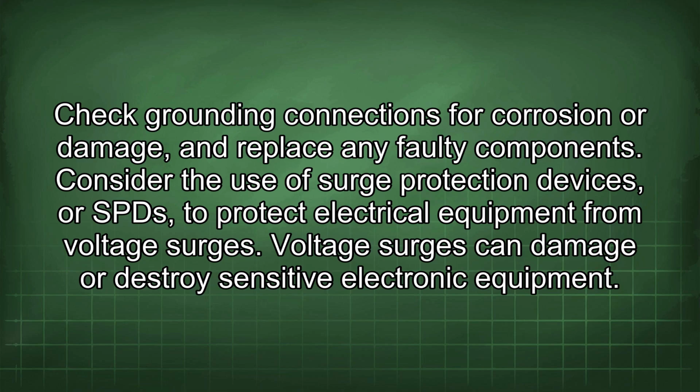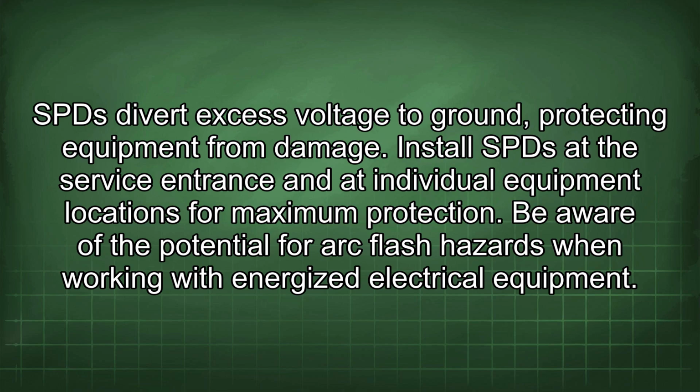Consider the use of surge protection devices, or SPDs, to protect electrical equipment from voltage surges. Voltage surges can damage or destroy sensitive electronic equipment. SPDs divert excess voltage to ground, protecting equipment from damage. Install SPDs at the service entrance and at individual equipment locations for maximum protection.